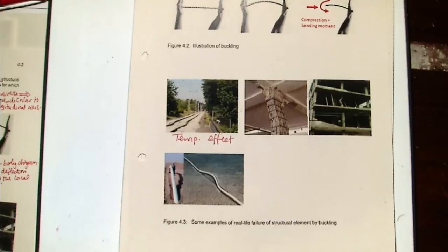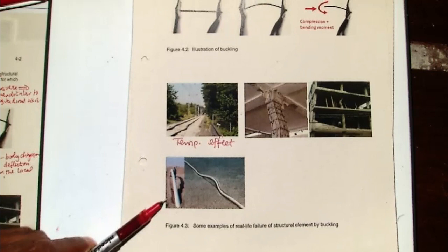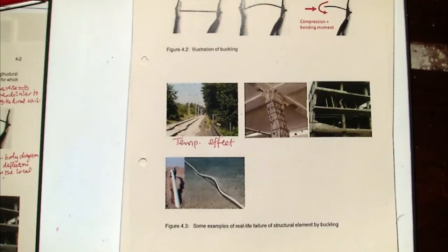So sometimes they are buried about 1 meter below the seabed. Because of the seabed, you have very high friction between the pipe and the seabed. So if the product that the pipe is transporting is very hot, then the pipe wants to increase in length, but because of the friction, it cannot do so. And therefore, you develop an axial compressive force.